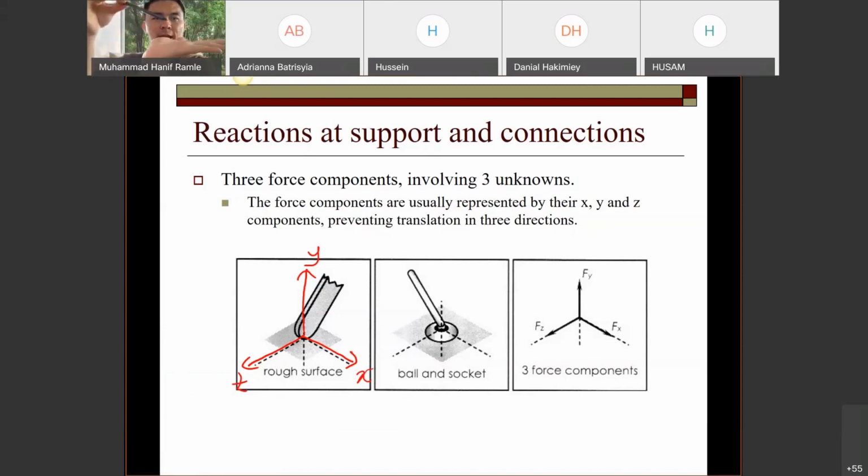My other hand is the floor. I put the rigid body on the floor. I cannot move this way because of the restriction, but I can rotate like this. I can rotate in any direction that I like. So there is no restriction on rotation, meaning no reaction.